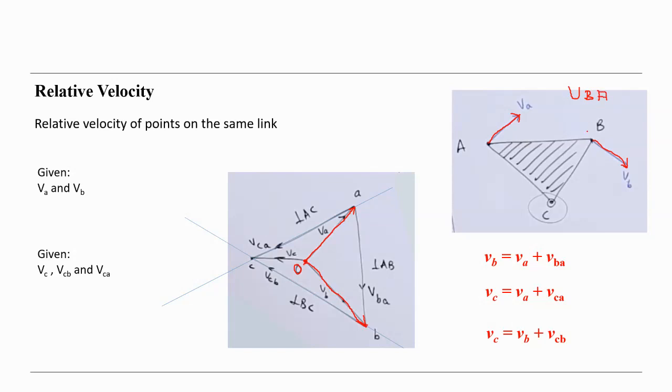This is the velocity of the point B relative to A. That means looking from the A, this is the rotation. Point B is turning, we assume, about the point A. So it must be perpendicular to this line AB, the direction perpendicular to the AB. And we can draw it like this here. This is the line here.